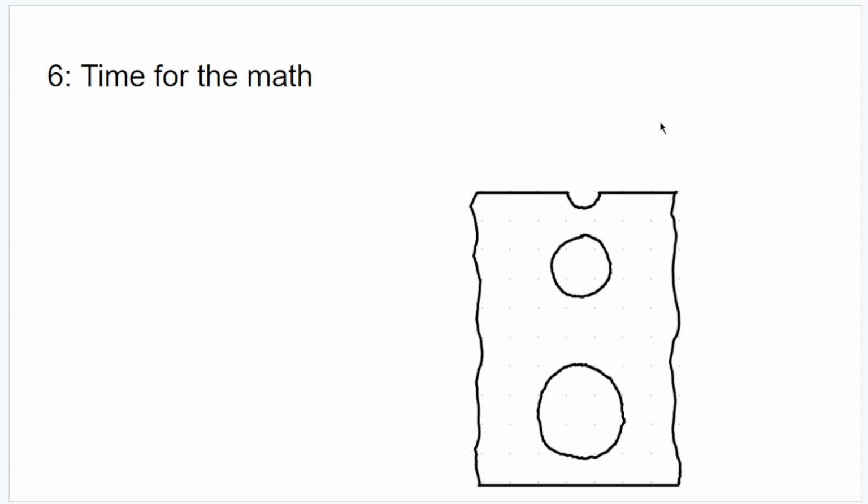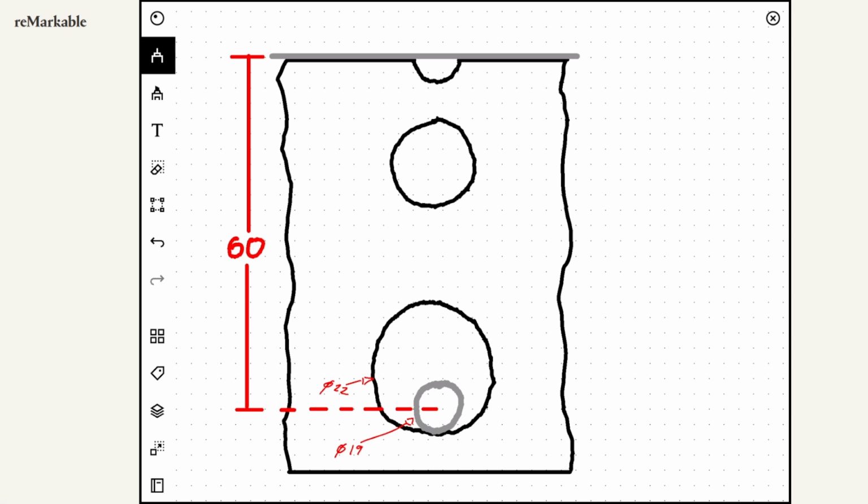And now it's time for the math, which I'm going to do live for you. All right, let's begin. So I'm going to do this by superimposing the first gauge, and then once we get to the point where we'd want to switch gauges for the calculation, I'll superimpose the second gauge. Let's start with our 0. And then I like to come in and make sure we don't forget about our form error. So we said that is 1 millimeter. Now we can start the interesting math.